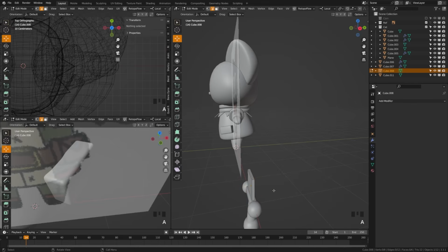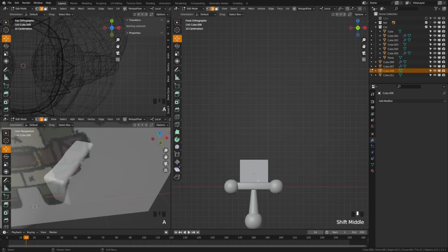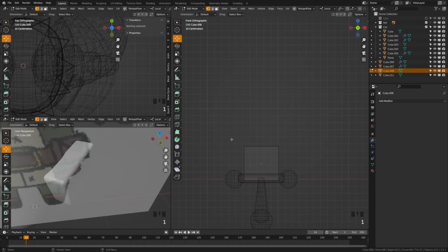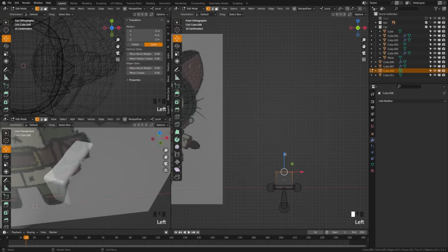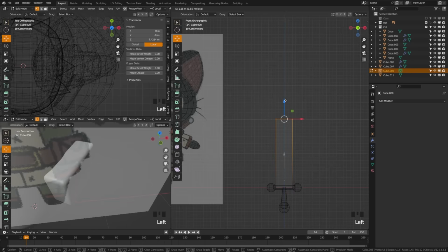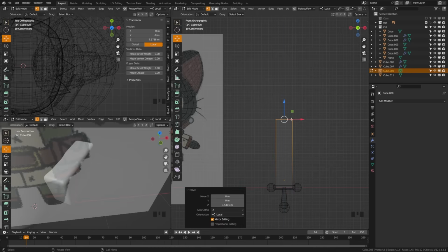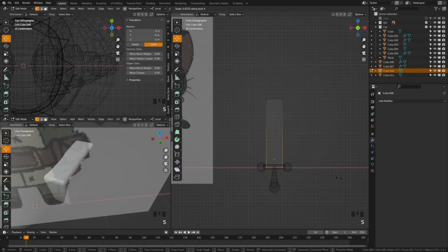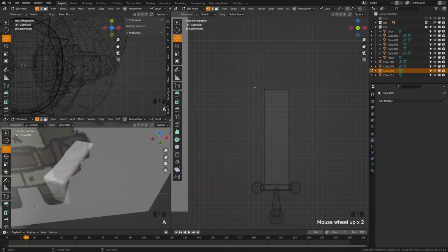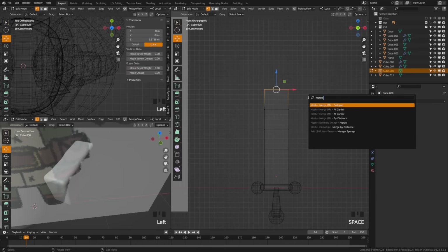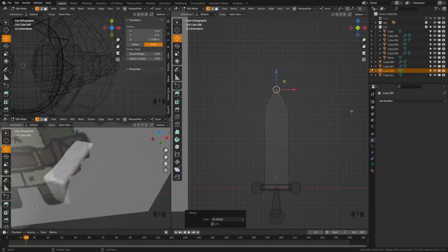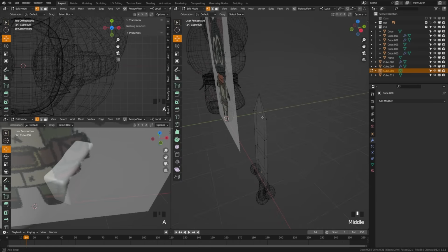And next what we're going to do is snap here in the front view, and we're going to switch to a wireframe mode, and grab these vertices here, and now what you want to do is pick the height of your blade. Perfect. That's about what I want. Now if you want, you can begin adjusting the shape here. I think I'm going to adjust mine a bit later. So first let's just hit Control R, scroll up on the mouse wheel, add a couple subdivisions there. Grab these top few vertices in wireframe mode and merge at center. And that'll give us a point at the top.